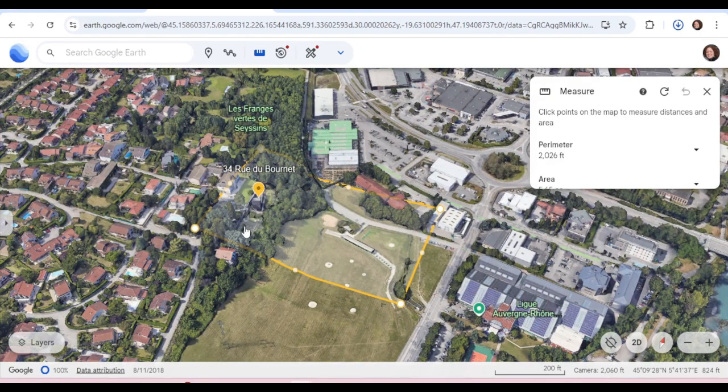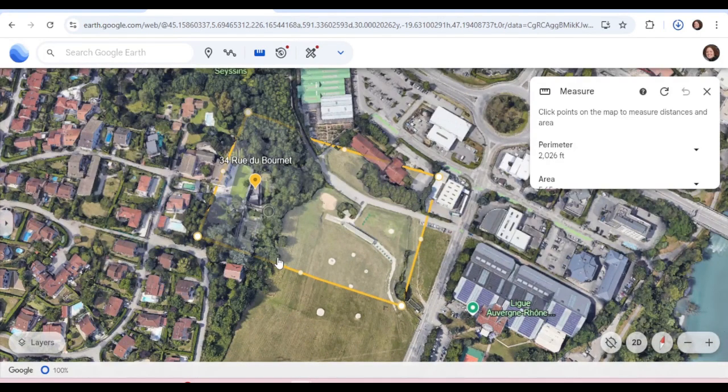The next thing that you will do is to develop a building pad on the upper left-hand side. Let's create a building pad that represents the base of this structure at 23 feet wide and 70 feet long.